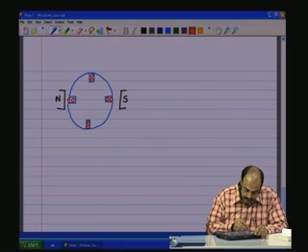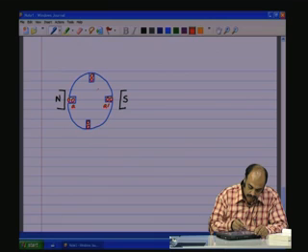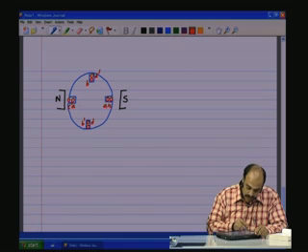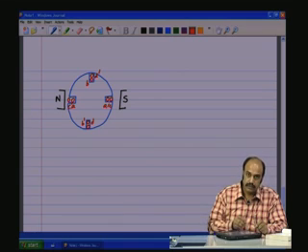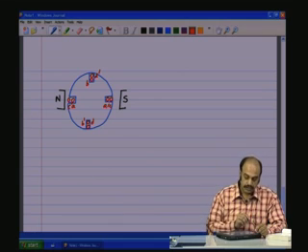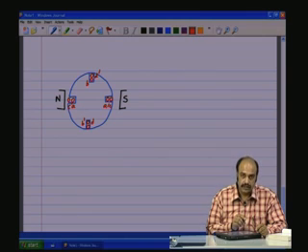This means that if there is a coil, let us say A dash, and then another coil here B dash, then again one more set of coil, let us say C dash, D dash, which means A and C are wound on the same slot, but having opposite direction of the coil winding.